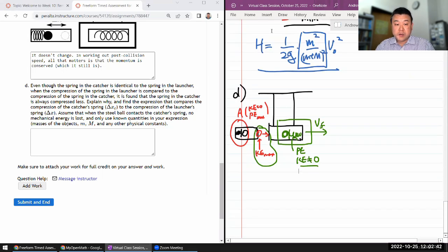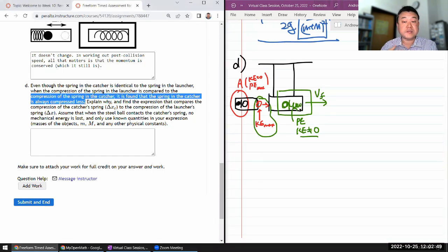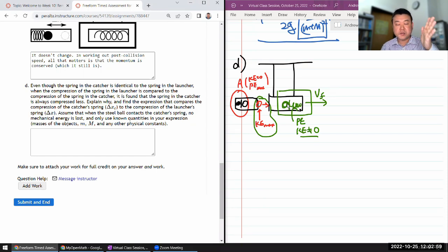In order to have the spring compress the same amount, you would need the kinetic energy to go back down to zero. Short of just supporting the catcher so that it doesn't move as it collides, it's not going to happen. While this was launching, initial momentum was transferred to the system, and until you take that out, it'll be required to have some kinetic energy. So yeah, that's the reason.